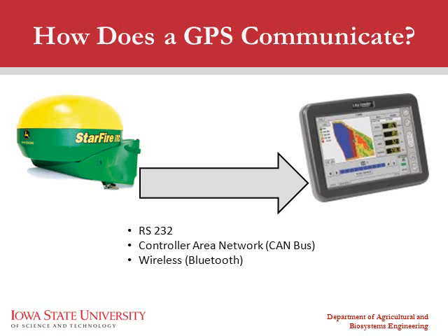The Starfire prefers to communicate over CAN bus, whereas the Insight from Ag Leader would prefer to have an RS-232 GPS input. The Starfire receiver can be configured for RS-232 to make this connection work, and is a requirement if we're trying to achieve communication with products that aren't based on the same generic protocol.